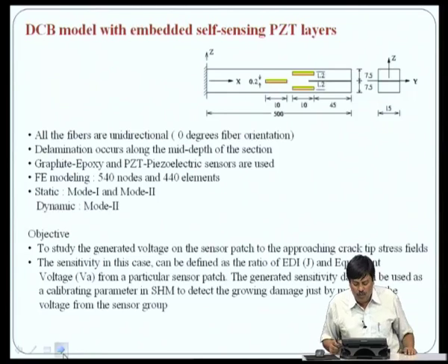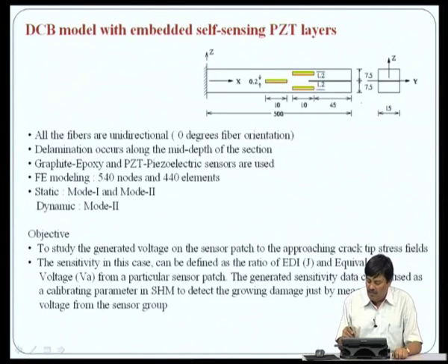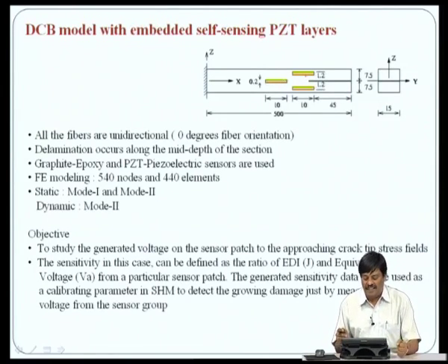So, here what we have done is we have taken a cantilever beam with a central delamination through width, and we want to see what is the piezoelectric sensor response, that is, what is the voltage that is developed as the crack starts propagating and goes inwards. What would be the sensor voltage that will be predicted in these 3 cracks, which is very useful to actually see whether there is something going on.